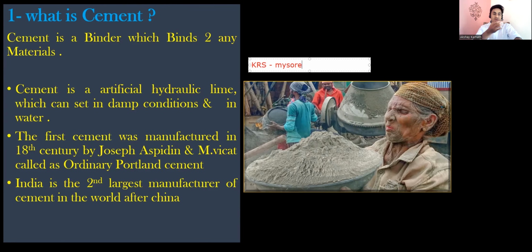And cement, and of course the lime, we use in a lot of construction. But the problem with lime is that it cannot set quickly. It will take a long time to set. The second is that lime requires an open environment. If I take one brick, put lime over it, and then keep a second brick, this lime will take a very long time to set. First, it is a slow set. Second, it is not getting enough environment. There's no flow of air to the lime, so the setting won't happen. So these were the two problems with lime.